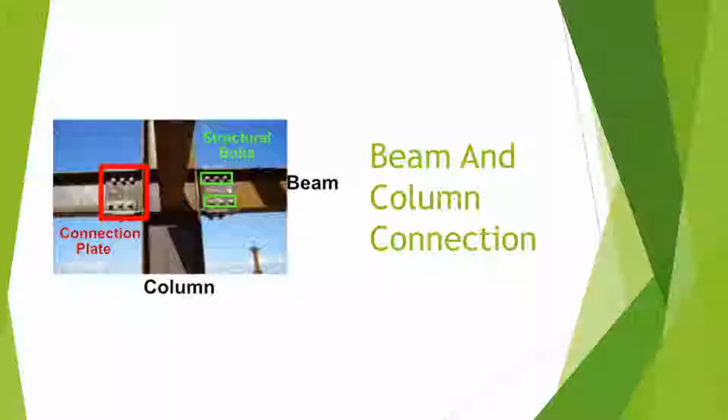Here, those guys are going to align the steel and insert bolts into those holes, connecting the beam to column via proper bolt pattern. This can take a lot of work. Sometimes those holes don't like to match up, but us as iron workers, we got the tools to align those holes so we can put those bolts through and connect.